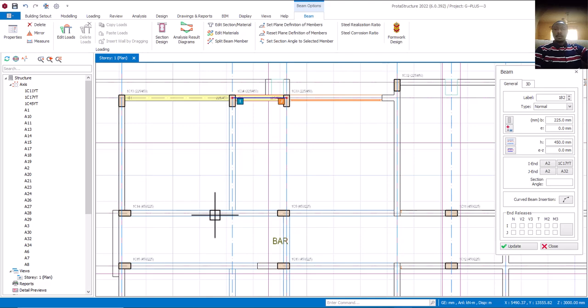Because at times if you want to move it, it might drag your drawings. Is that okay? So half of 2 to 5 is what? Press F2 first, then 112.5, enter. Correct, which is this one. So I'll click on this one now. Click on this, delete it.